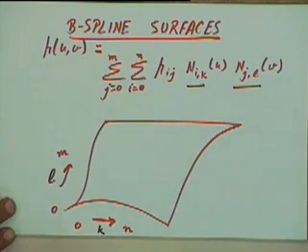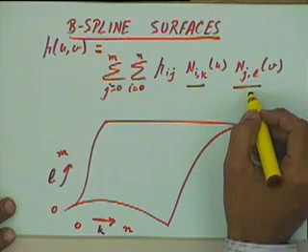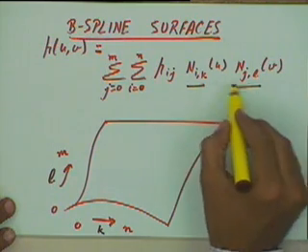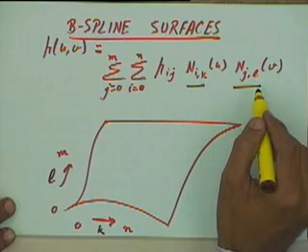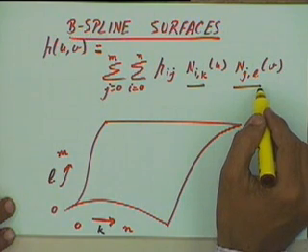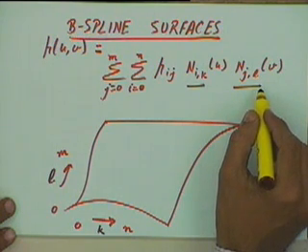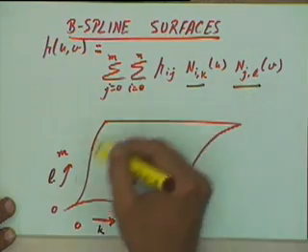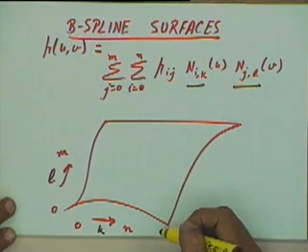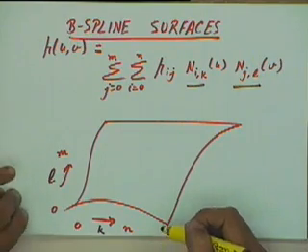So if you are defining a bicubic B-spline surface, we will put k equal to L equal to 4, that will define a bicubic B-spline surface, and the number of points in either direction can be anything. So we will be able to define an array of surface segments or surface patches as we are defining curve segments for B-spline curves.